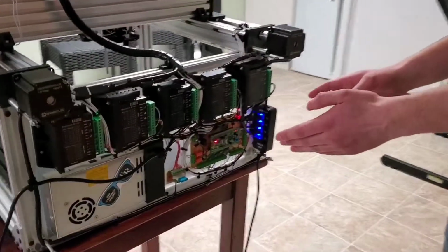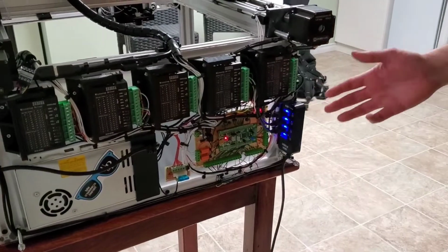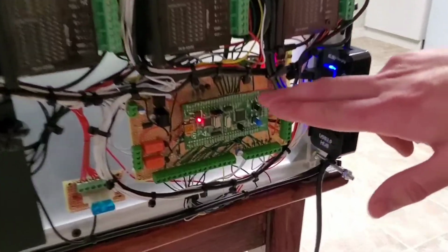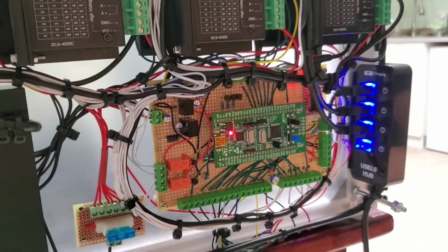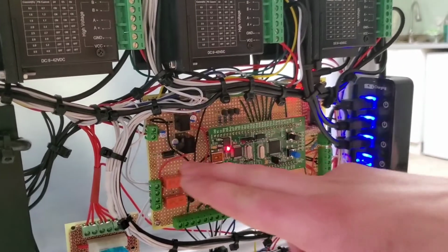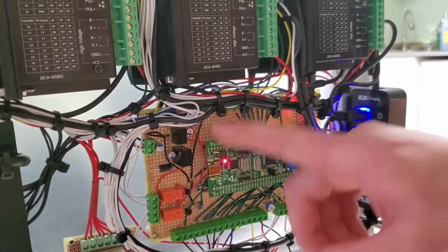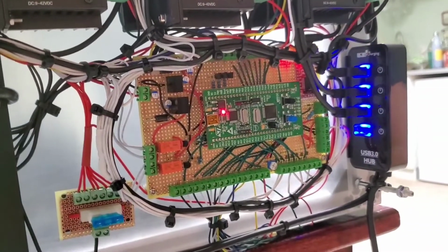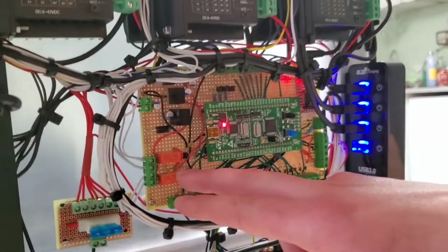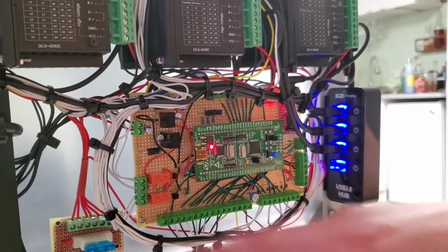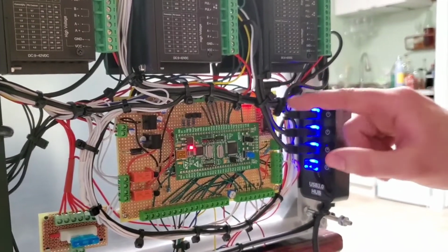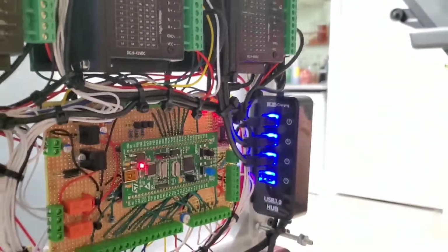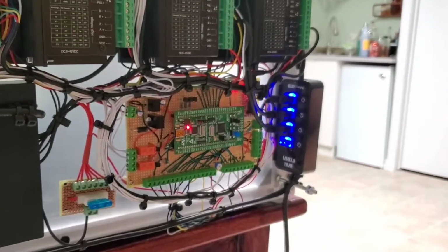Now, the protoboard itself is effectively just a breakout board for the STM with a few other components on it. So as you can see in the middle here, we have the STM board itself. Over here we have all of the power supply components. That's a 3.3 and a 5 volt Recom and linear regulator, as well as a 12 volt Recom to control the lighting. Over here we have MOSFETs and relays which control the lighting. Over here we have a USB to serial converter. I'll elaborate on this more, but this effectively allows the PC to communicate with the STM.